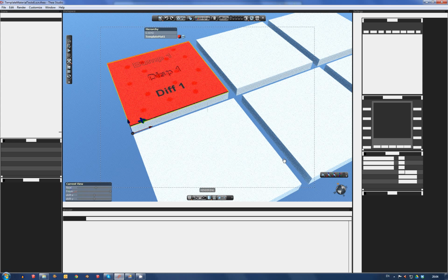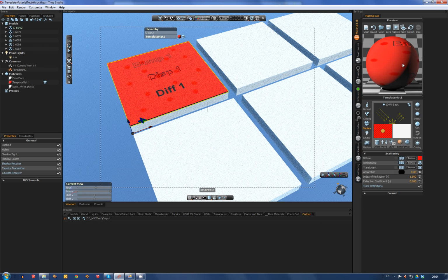First thing you do is you go to Thea and make a complete first material using, for example, floor 1's materials. You'll use those bitmaps and also set things like the bump strength, the displacement height, other settings like layers and glossiness. I've got the bitmaps used in the various slots here. I've also got another one in this reflectance slot, which we're not going to change across the variants, just for demonstration purposes. All the things like the bump strength and the displacement height and glossy layers and whatnot, they're not going to be changed across the variants. Only the bitmaps are changed.